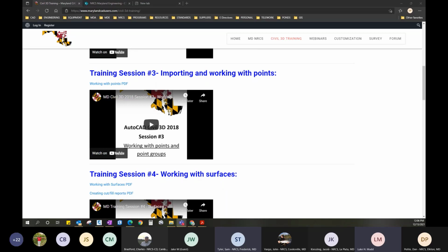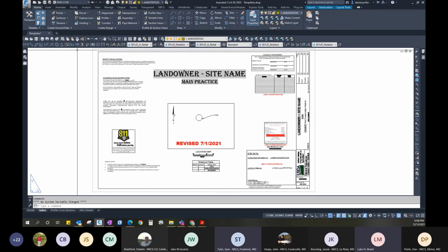There's a command, and there's a button. It's called Match Properties. If you can get familiar with that command, and you get confused with setting up your text style and text dimensions, as far as whether they're readable or not, 0.10 or 0.12, get one that you can read, and then just match that property all the way around. That's going to save you a whole lot of time trying to go back to basics again.